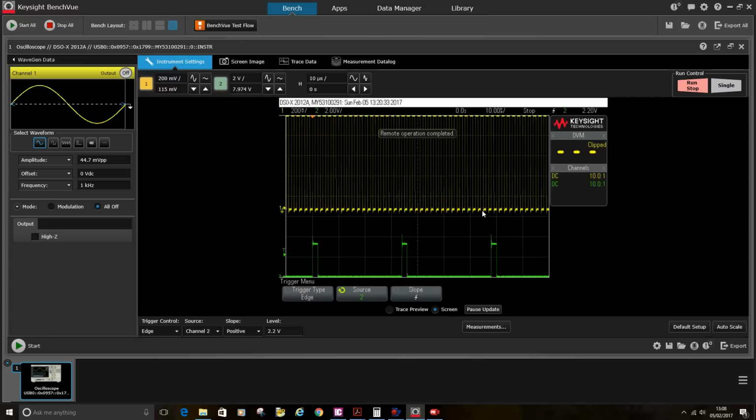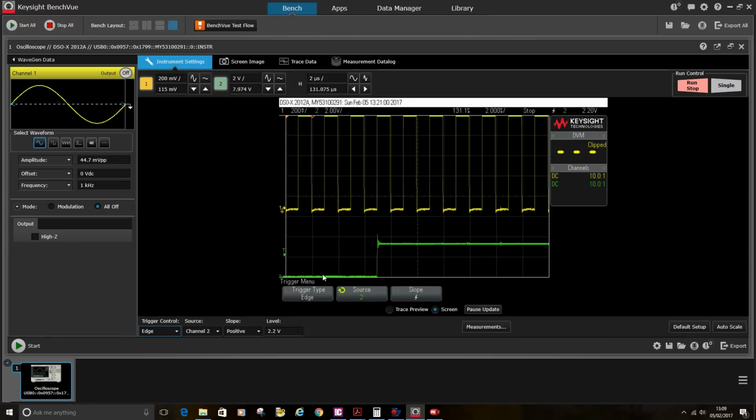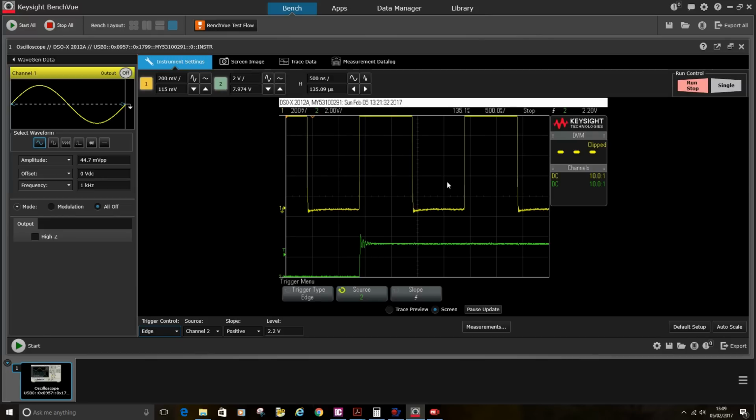Now if I run to the end, I've run to the end of the frame. So look, this is the end of the frame, and now that's my 5 bits written. Now look at the frame select, bang on when that's the last clock of the 16th clock. There's no delay there at all. It's probably overlapping. Let me zoom in a bit more. Look at that. So I'm zoomed in to 500 nanoseconds, and there is no delay at all. It's actually turning off probably a bit before, but you're allowed to do that. You're allowed to turn off in the middle of a clock.